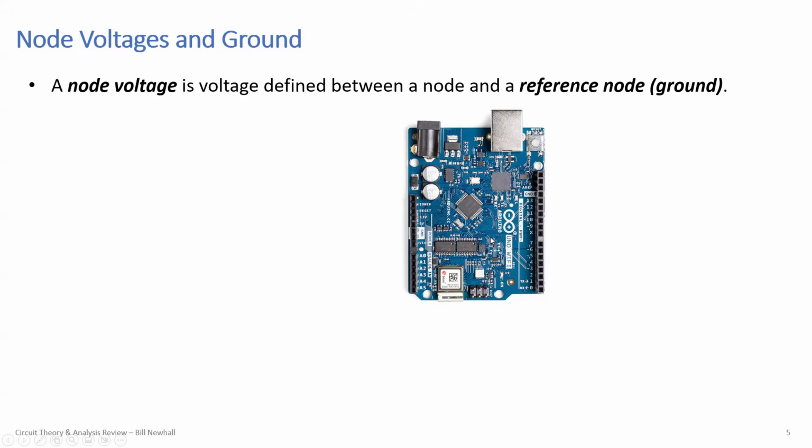This is an inertial measurement unit, IMU. It's 6 degrees of freedom, which means it has X, Y, and Z acceleration and X, Y, and Z axes gyroscopes built in. So this is the board we'll be using. You'll see you have access to the terminals here. This is called a header. These are holes into which you can stick breadboard wires and then solder to those wires or run those to your breadboard to have access to the signals of the microcontroller.